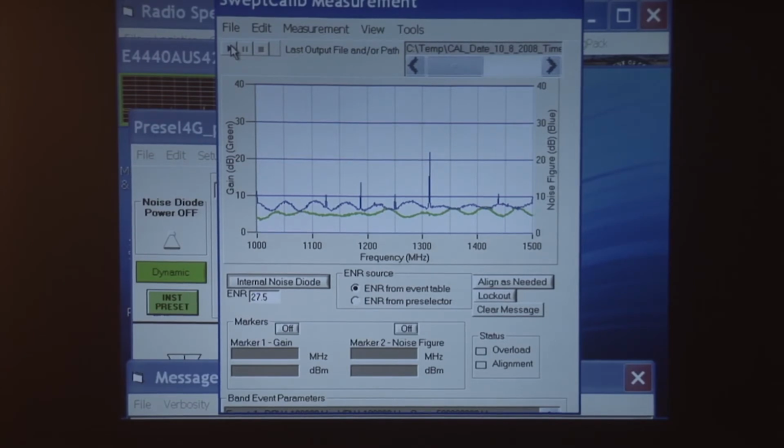Now let's see what happened. Huh, isn't that interesting? Our gain values are a little higher. They're about 5 dB now, so that's about 1 to 2 dB higher than they were. But not only did our noise figure not improve, our noise figure has actually degraded by about a dB or 2. So, just sticking an amplifier into a system doesn't always solve all your problems.